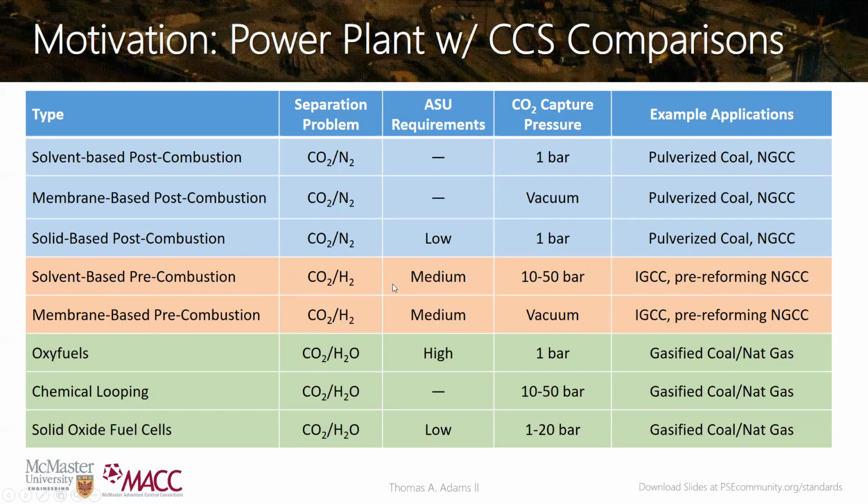So these solvent technologies have been around for a very long time. It's just that now we want to use them in very large measure for CO2 purposes. And the nice thing here is this can happen at high pressure, which means the captured CO2 is at a higher pressure for sequestration. And you can also use membranes. The CO2 hydrogen membrane can be more effective than CO2 nitrogen in many cases.